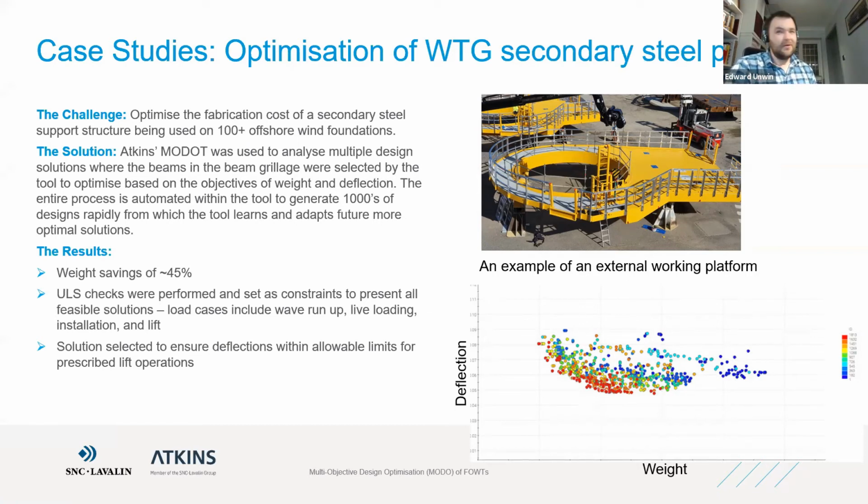We were thinking we might get 20%, but it just shows something that you thought was a pretty good design, because it's broadly what the last one looked like, and it meets all of the code check criteria without too much fat in it. You feel like it's a reasonably good design, but actually it can be an awfully long way from optimal against what we consider in this instance to be the really important criterion, which is weight.